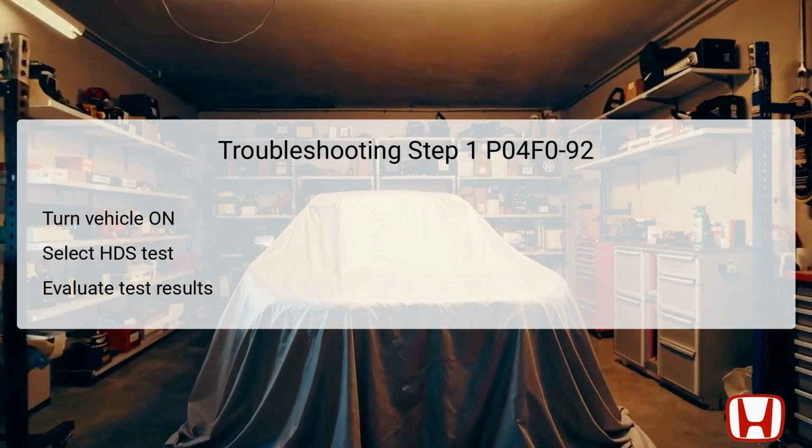After executing this test, it is important to carefully evaluate the results. If the test results show that the purge flow is not within acceptable parameters, this indicates a failure that necessitates further investigation into the associated components.